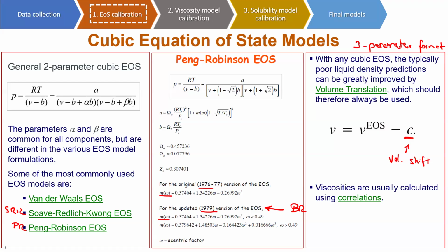So when you try to calibrate the equation of state and compare the prediction of the API, the density of the dead oil, the default prediction before the tuning and after the tuning, the values are completely different, because to predict accurately the API, you need to include this third parameter in your equation of state.